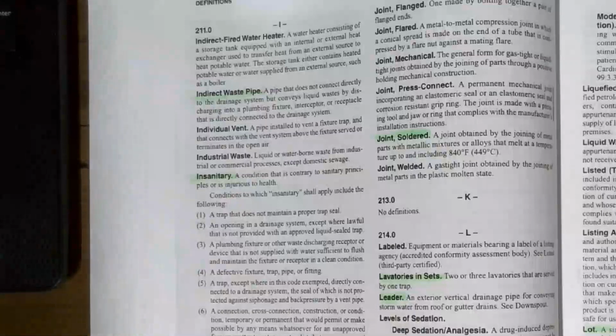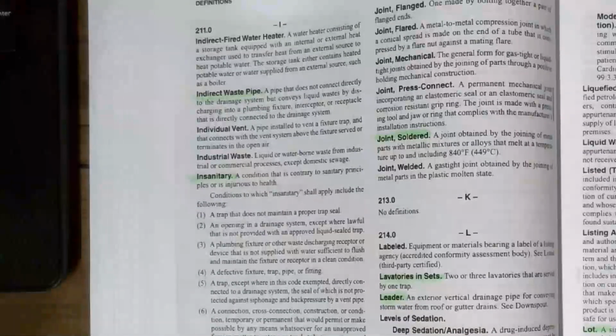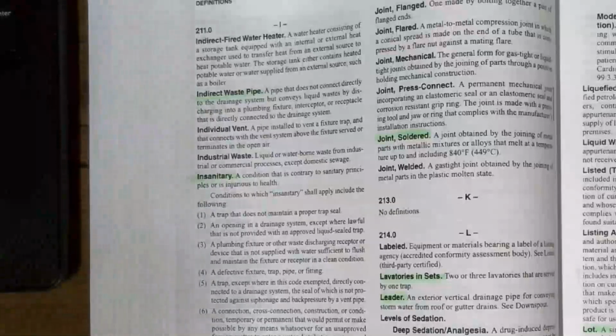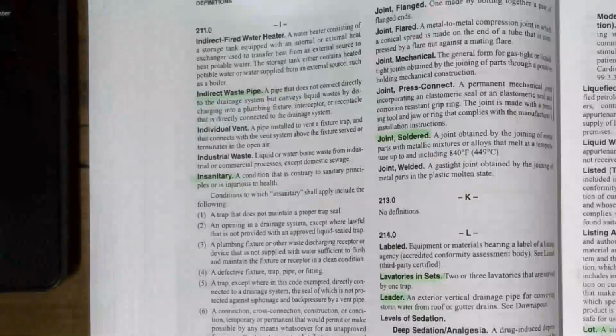So you have pipe that's running across the ground and it drops into a floor sink, which is like a large, deep floor drain. And that's connected to the wasteline. And the purpose of that is if there ever is a sewage backup, it's not going to contaminate the fixture, because the sewage backup just goes out onto the floor. The indirect wasteline has that air break in there and an air gap of at least an inch. Depending on the size of the pipe, it's actually going to be larger. But that air gap that is installed by us protects the fixtures, and it's always in a commercial restaurant, something like that, in the kitchen. That's usually where indirect waste is.